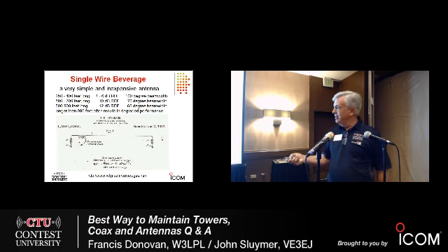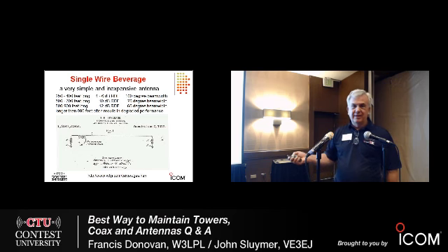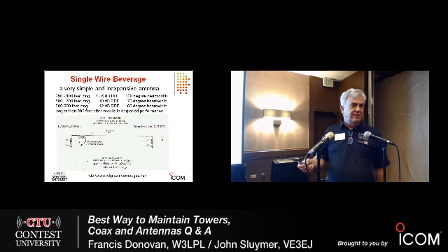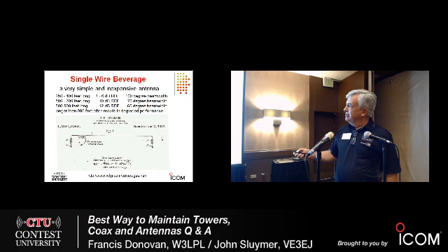And he continued to develop it, and to make a long story short, came up with the thing we would recognize as a Beverage today, with a matching transformer at one end and a resistor at the other end. His was miles long. It was operating at 40 kilohertz or so. We're at 160 meters, so we're only dealing with maybe 500 feet, and his were dealing with antennas that were long, that looked like a telephone line at the time. 1920. Quite good RDF with a Beverage.